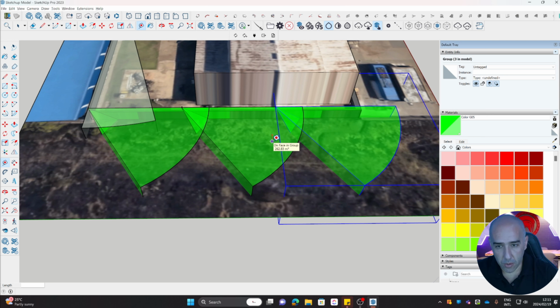Why would I also do this? The cost of 3 cameras, 3 poles, extra cable, more labor would probably come up more expensive than putting in 1 thermal and 1 color view in the corner. You would have to explain this to your client, ask him for his opinion. He might say, you're the professional, you tell me. So you would go and say, okay, I'm going to put another thermal in, it's going to save you money and it's more effective because we're looking for body heat. That would be the solution.